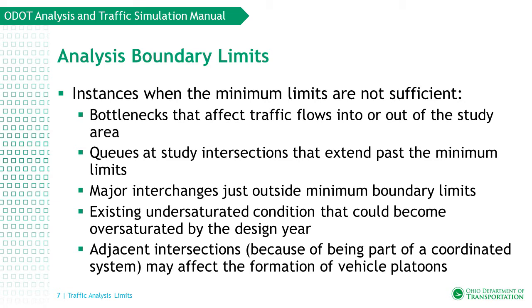Major system service interchanges just outside the minimum boundary limits. These large interchanges could affect the lane changing behavior in the study area and should be included in the model limits. Existing undersaturated conditions that could become oversaturated by the design year. Expansion of the analysis boundary should be considered to ensure the model limits will be undersaturated in the design year.